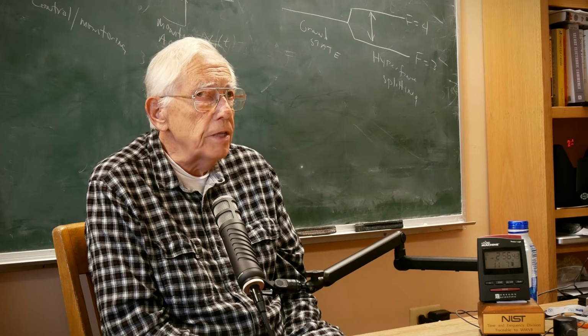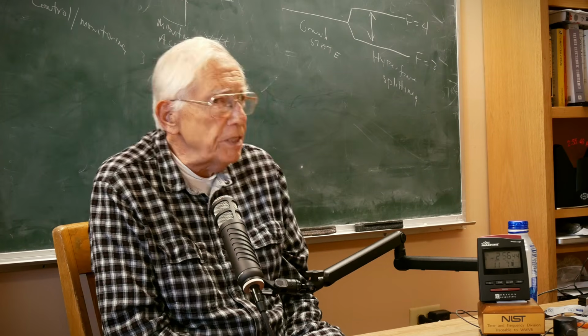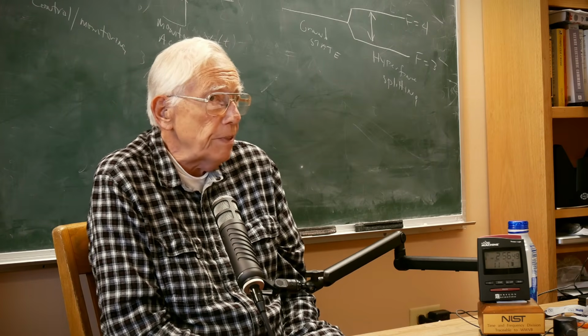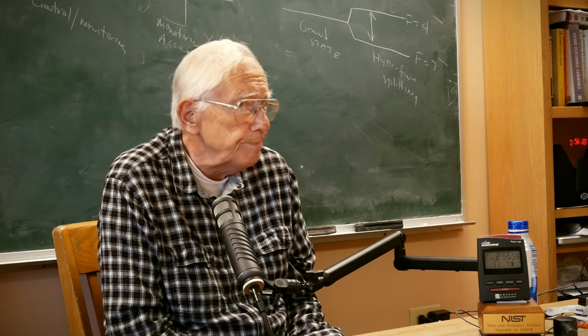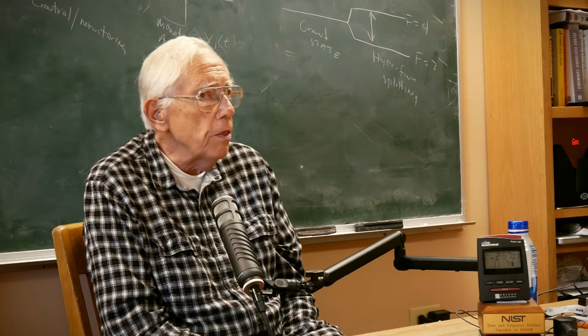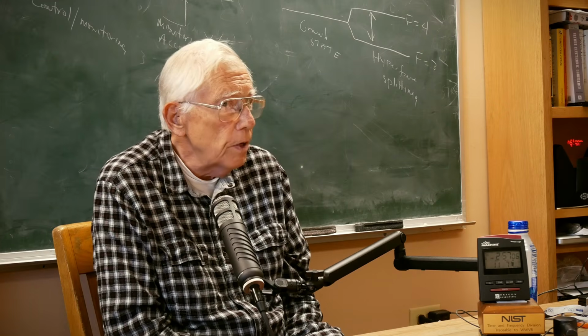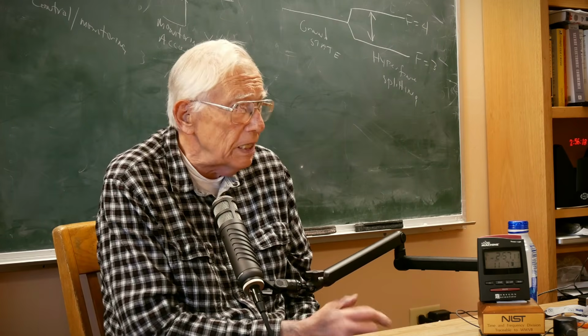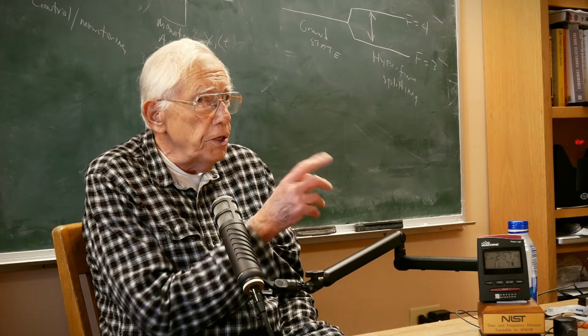Well, I think the frequency that you're counting depends on what kind of device it is. For example, if it's a pendulum clock. That's what I was thinking. In a pendulum, you can just connect it to an arrow and it goes like this. Well, no, but the pendulum clock has a thing called an escapement. It's the gear that clicks every time the pendulum swings. Exactly. So the counting is done mechanically. Whenever the pendulum swings, the escapement advances by one click, and those clicks are used to drive the hands.